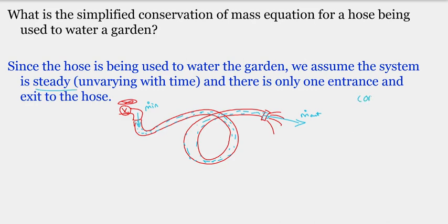So again, to develop good practices, always start with the most general form of the equation. Don't simplify it on the fly. That's where you make mistakes. So always start with your expression for a control volume, which says the change in the mass within the control volume is balanced by all the mass in and all the mass out. Then you can simplify. And then you can even keep track of your approximations and simplifications. You can say, hey, that's a steady system. So there is no time variation, and that term is equal to 0.